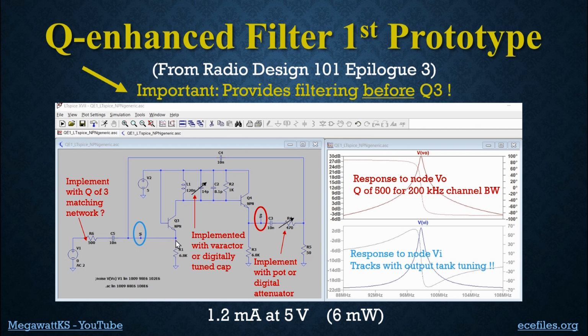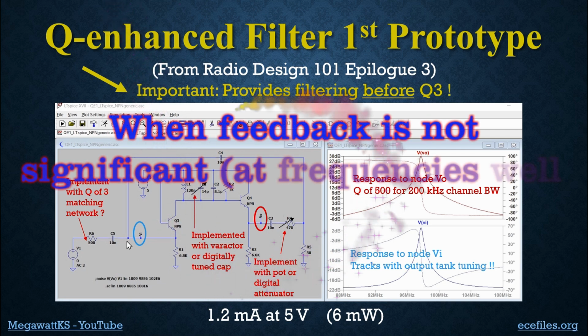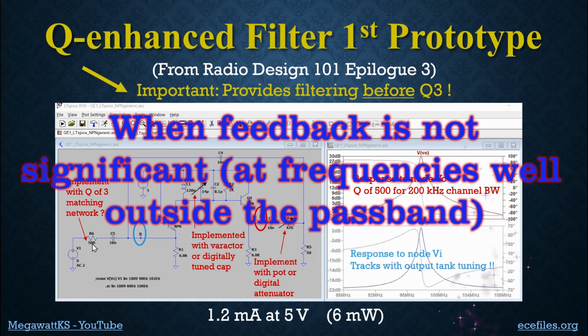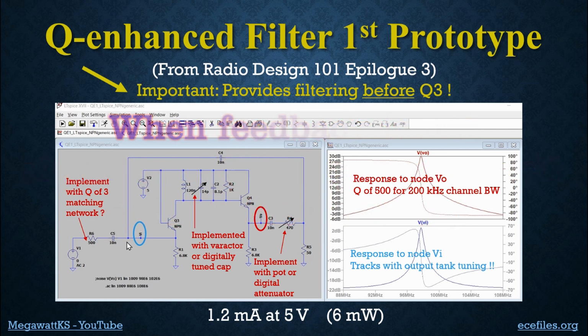Now, this thing was designed to have about a 50 ohm input impedance, but if you trace this line back, you see there's a 50 ohm resistor to ground here, so that means the net impedance looking into this thing is about 25 ohms. Ooh, we got 500 ohms driving into 25 ohms. That's going to create a huge attenuation.